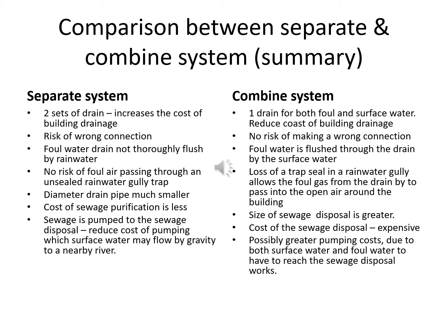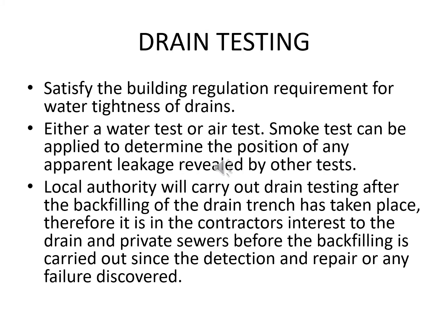There is the possibility of greater pumping costs, due to both surface water and foul water having to reach the sewage disposal works. The drain testing is to satisfy the building regulation requirement for water tightness of drains, either a water test or air test.